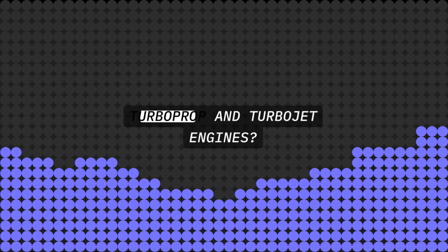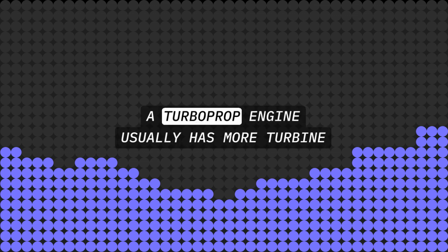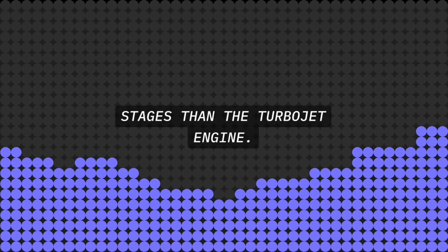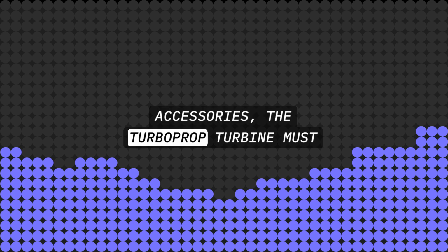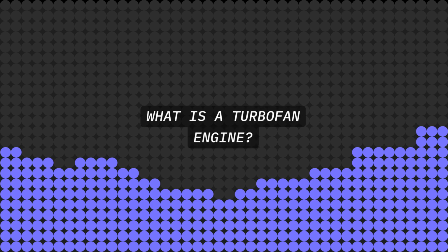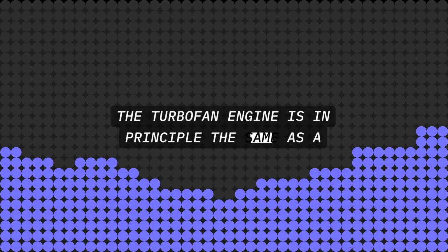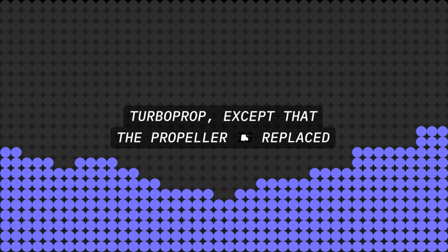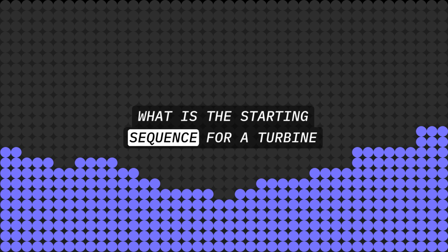What is the major difference between turboprop and turbojet engines? A turboprop engine usually has more turbine stages than the turbojet engine. In addition to driving the compressor and accessories, the turboprop turbine must also drive a propeller. What is a turbofan engine? A turbofan engine is in principle the same as a turboprop, except that the propeller is replaced by a duct-enclosed axial flow fan. What is the starting sequence for a turbine engine?